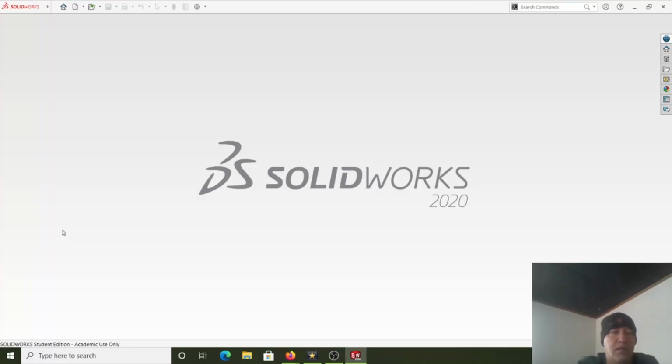Alright, today we're gonna work on building a tombstone. Just a basic one. This is strictly designed for entry-level assembly packages. So first of all, we've got 6 parts to a tombstone: base plate, top plate, and 4 sides, or at least a typical tombstone. So again, we're going to start with, each part has to be modeled individually.